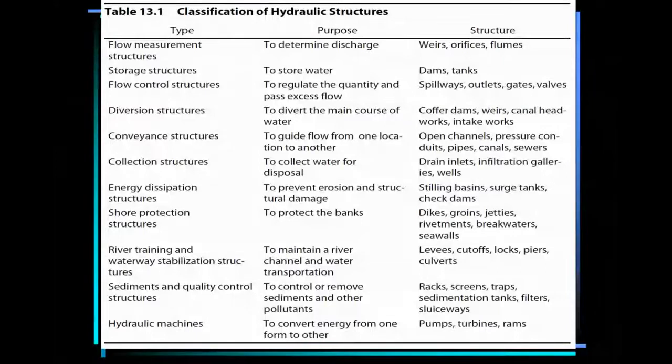Just like a sedimentation tank in a water treatment plant, in which water is collected after coagulation. After you apply the chemical that will reduce the zeta potential of the floc, so that the particles, the sediments, can come together and become bigger, you pass it over to the sedimentation tank where the floc will settle down. And the clear water will move out of the sedimentation tank.